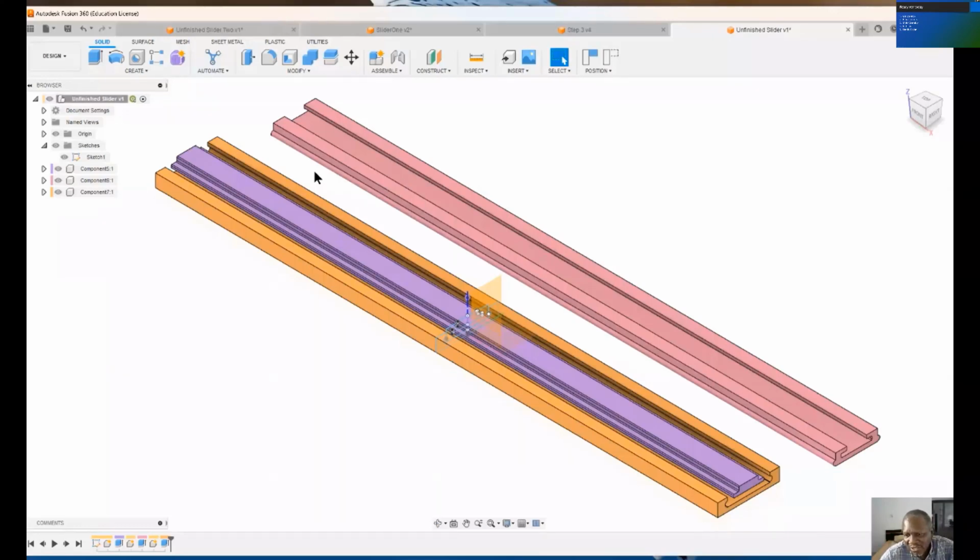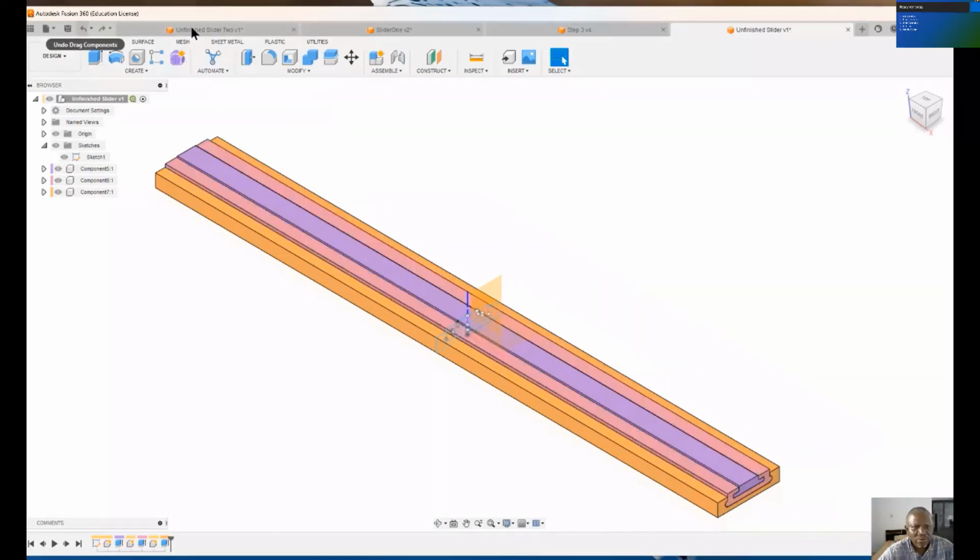Don't forget that Fusion 360 is just a drawing. So it is for us to now implement and enforce constraints that will make it move like a real body that we are used to in reality. That is what we are going to try to do now. And in order to do that, we are going to implement what we call joints inside the assembly process. So we take assembly and we select as built joint.